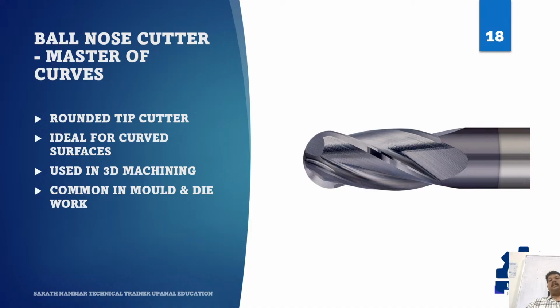Now imagine trying to machine a sculptured curved surface using a flat end mill. You may leave steps, marks, or awkward transitions. The ball nose helps create a smoother result. That is why in the mold and die industries this cutter is highly respected. It may look simple, but it unlocks advanced geometry.